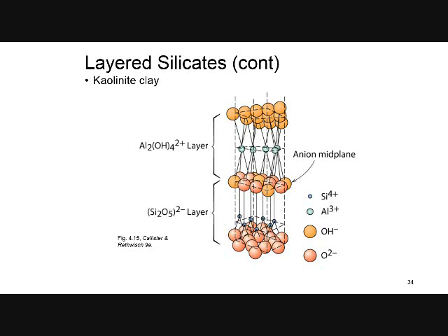It's a layered silicate mineral with one tetrahedral sheet of silica, SiO4, linked through oxygen atoms, as you can see here, this pink color, to one octahedral sheet of alumina. And the one here is the alumina. Bear in mind that the adjacent sheets of this type are very loosely bound to each other because there is a van der Waals force between them.